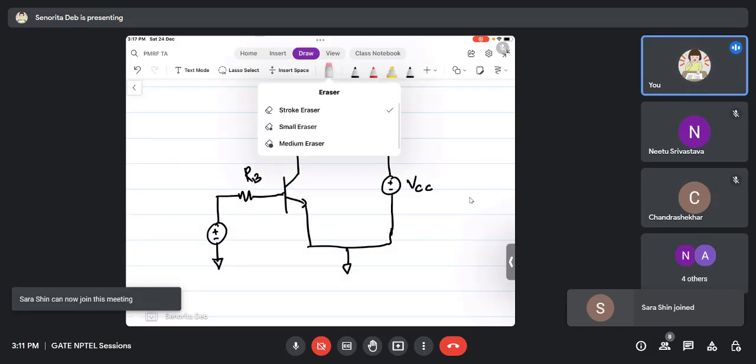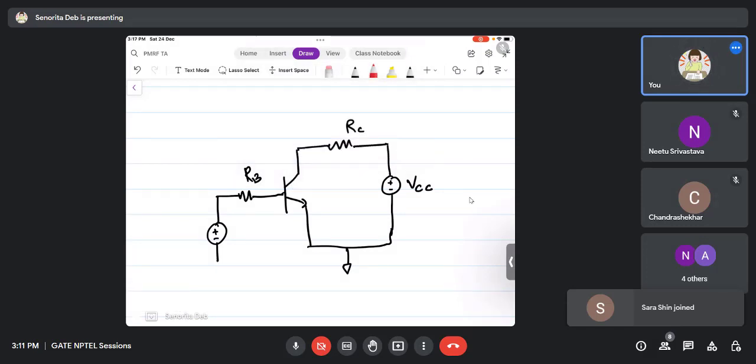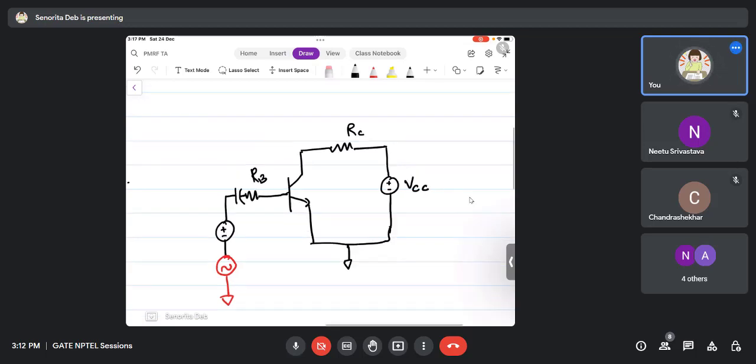Now you tell me how you amplify a signal. So what you do is you connect an AC source here along with the DC. The DC has to be there. Okay, and therefore we have to use a coupling capacitor here, so that the signal gets coupled. When we are doing the AC analysis, the signal can get coupled to the base. That is the reason why we use this cap. And again at the output we use another coupling cap, and from there we observe the output across whatever. You can use an oscilloscope or you can use a resistor also.